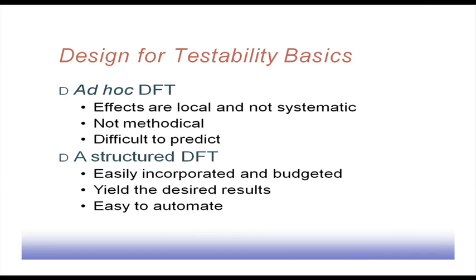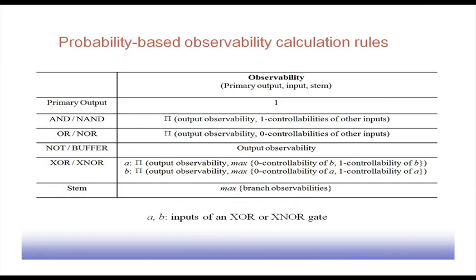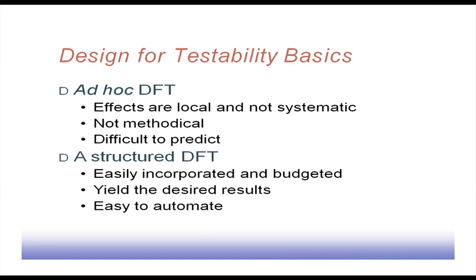Now, for DFT design, there can be ad hoc designs. The effects are local and not systematic. We just observe something, and accordingly we do some local modifications so that the testability becomes better. It is not methodical.